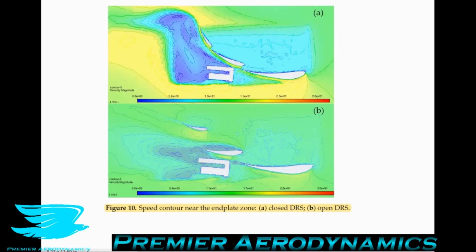Like 0.086 is pretty decent. The lift coefficient is still very high. It's 0.54. So getting that much lift out of this system with such a low drag coefficient is quite good. But why do we get such a high lift still? The reason why is because these airfoils are not symmetrical. They're cambered. So they are obviously going to produce a downforce, even at 0 degrees angle of attack.